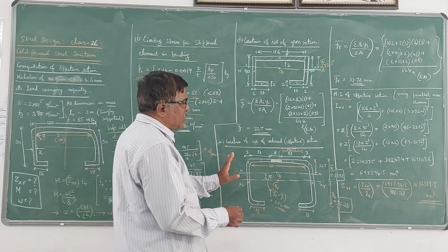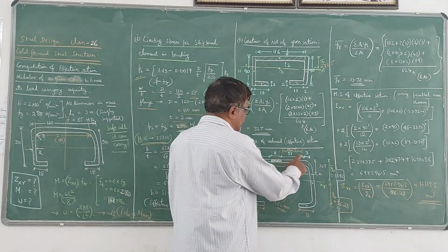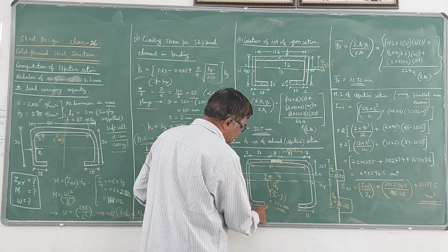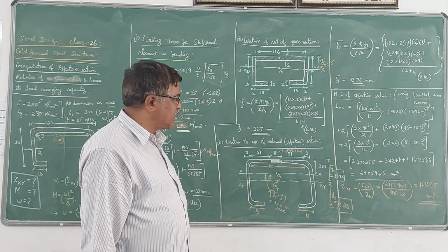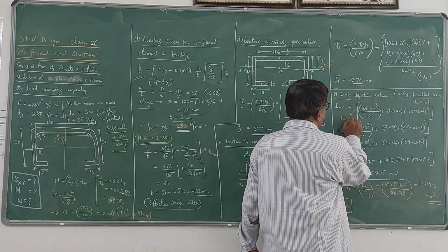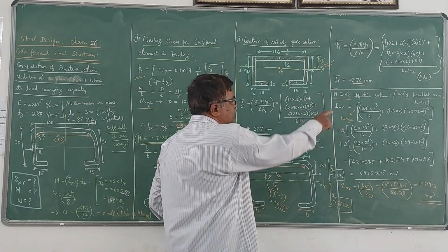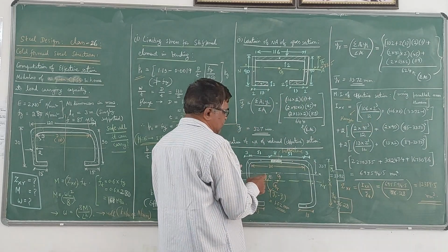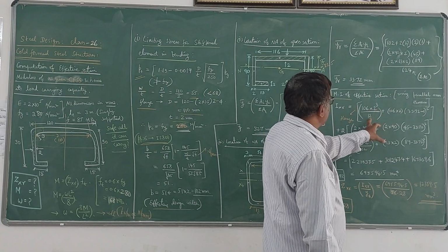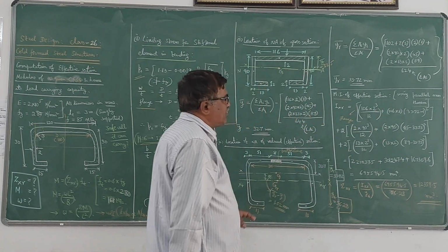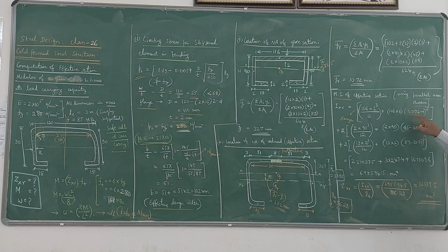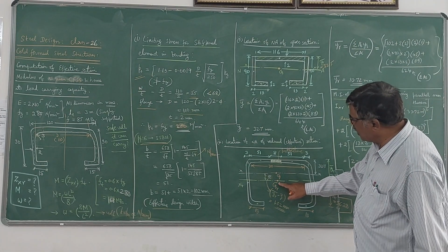Now according to that, what I have done here is I have taken the rectangle for the flange separately, and the two rectangles for the webs separately. The two lip portion rectangles I have taken separately, and I have applied the parallel axis theorem. So this first part is for the flange. As per the parallel axis theorem, it is width into depth cube by 12. So width is 106 now. So 106 into 2 cube, the thickness becoming the depth, divided by 12. Plus the area of that flange, 106 into 2, into the distance from GR to the centroid